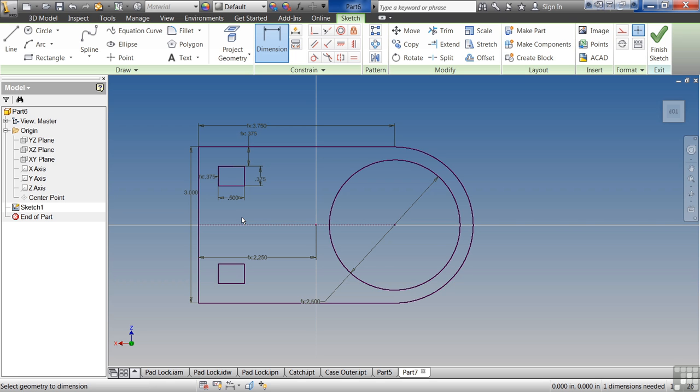Remember, capture it early, capture it as simple as possible, and you want to capture the constraints before you capture the dimensions. Basically, what shape should it be before what size should it be? And if you notice, the very last thing we do is the size. AutoCAD users, this is the opposite of what you're used to, and this is very hard for you to get used to. But sketch it out very roughly. Doesn't need to be pretty. It doesn't need to be nearly the right size. Create the shape you want by using the dimensional constraints, perpendicular, parallel, tangent, symmetrical, and then add your dimensions and define the size of it.